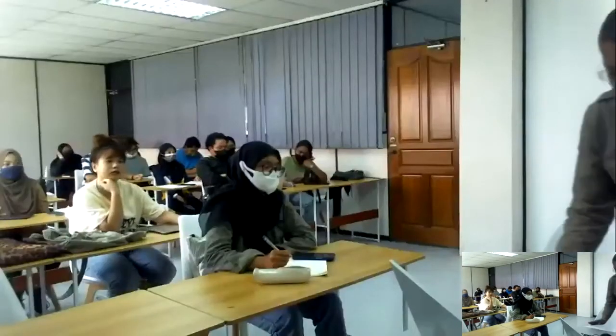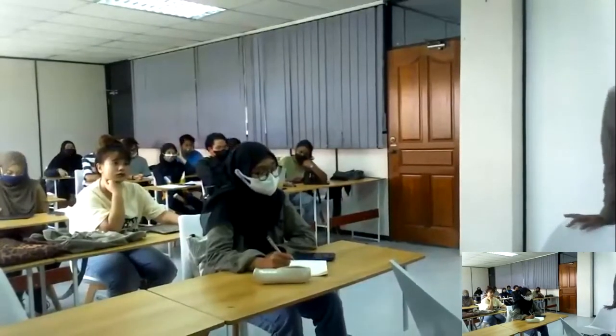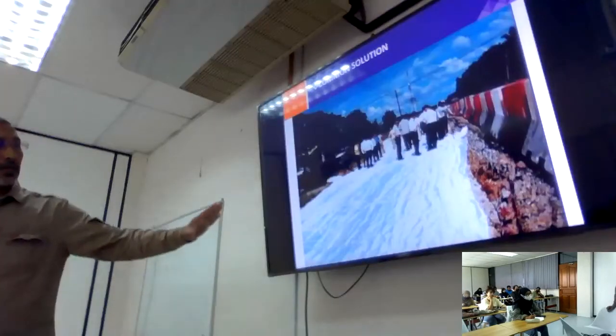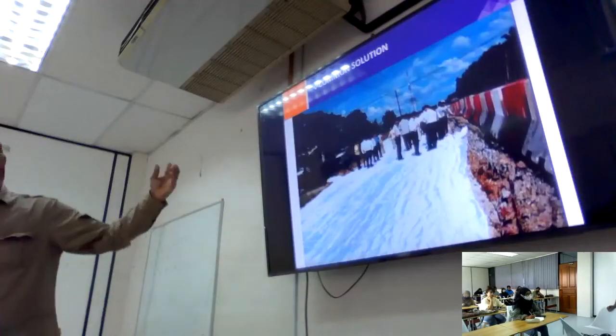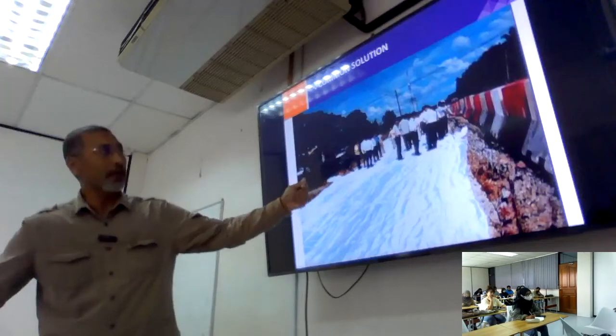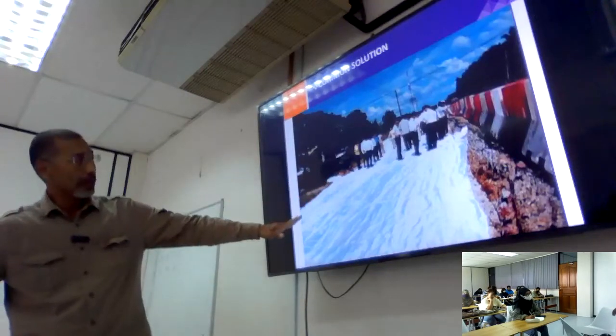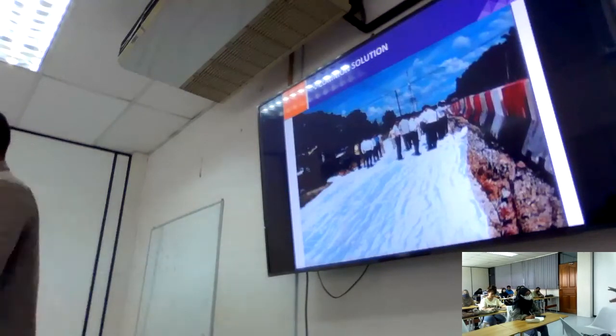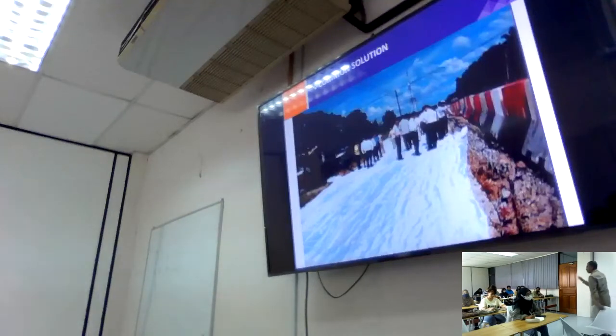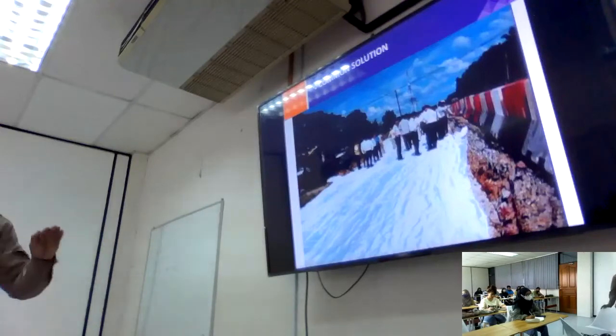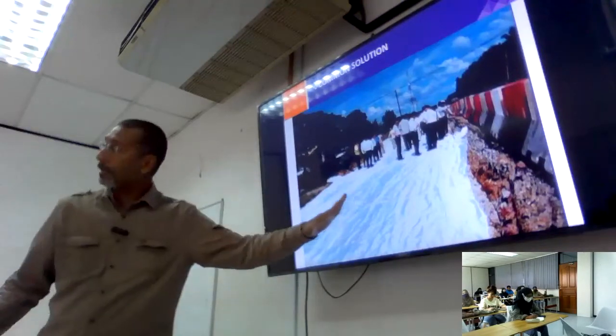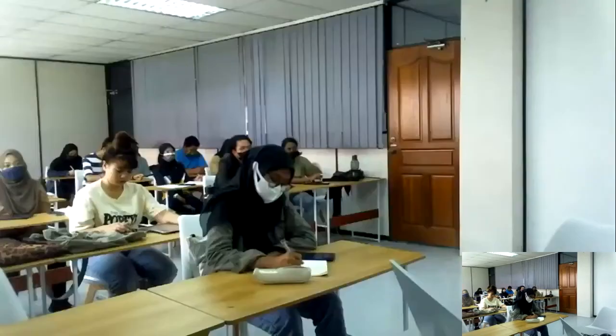So there is some common solution that is commonly used, similar to this one here, which is the use of geotextile, similar to the one that we saw just now. This is the actual work in Kuala Selangor. In Kuala Selangor, the road is really bumpy. Anyone from Selangor, you know that. So we need to separate the existing soil, which is weak, from the imported soil that we use as embankment.